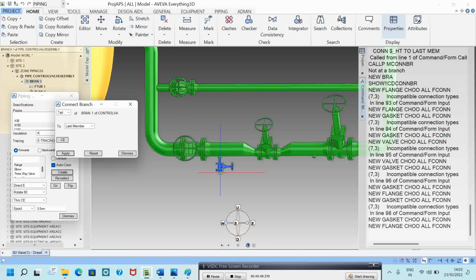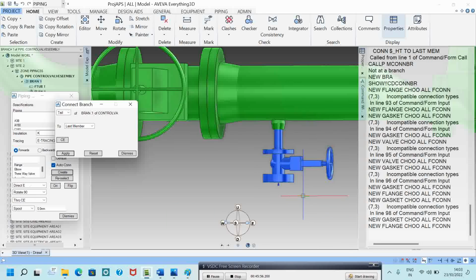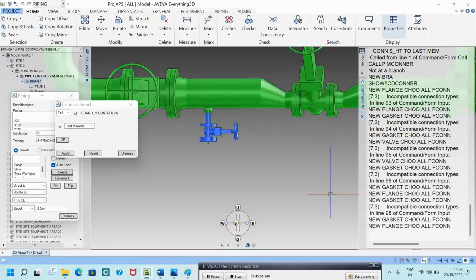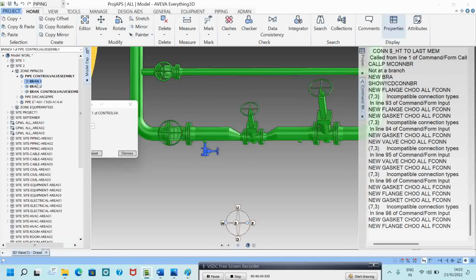So the distance from this blind to the FGL, floor ground level, should be minimum 150 mm. Okay, so while we are modeling, we have to check all those things. Okay, so what I do, I will just keep this one. I'm not making again the 3D model. I just show you how to copy paste. Okay, just here make copy, here just paste, click this one.